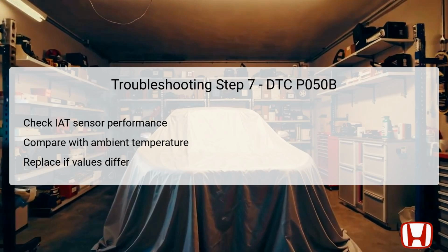necessitating its replacement. If the IAT sensor readings are as expected, examine the throttle body for dirt, carbon buildup, or any visible damage, as these could also contribute to ignition timing problems during cold starts. Clean or replace as needed to ensure optimal functioning.